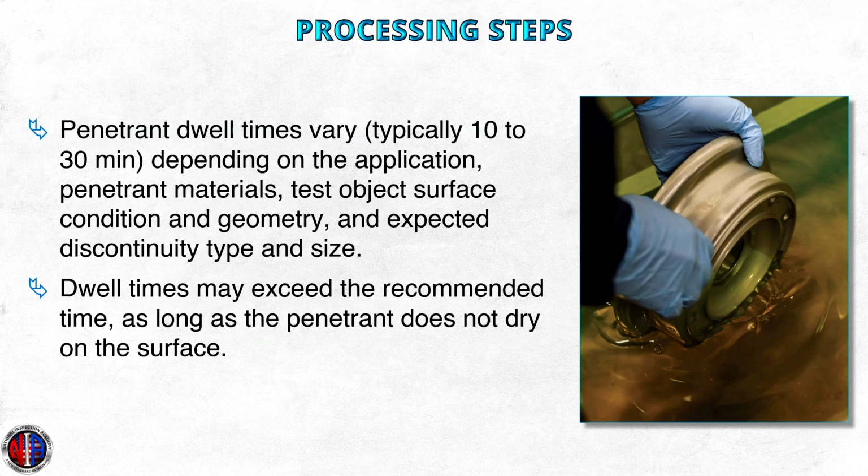Dwell times vary, which are typically 10 to 30 minutes, but depend on the application, penetrant materials, test object surface condition, geometry, and expected discontinuity types and size. Dwell times may exceed the recommended time if permitted, as long as the penetrant does not dry on the surface.